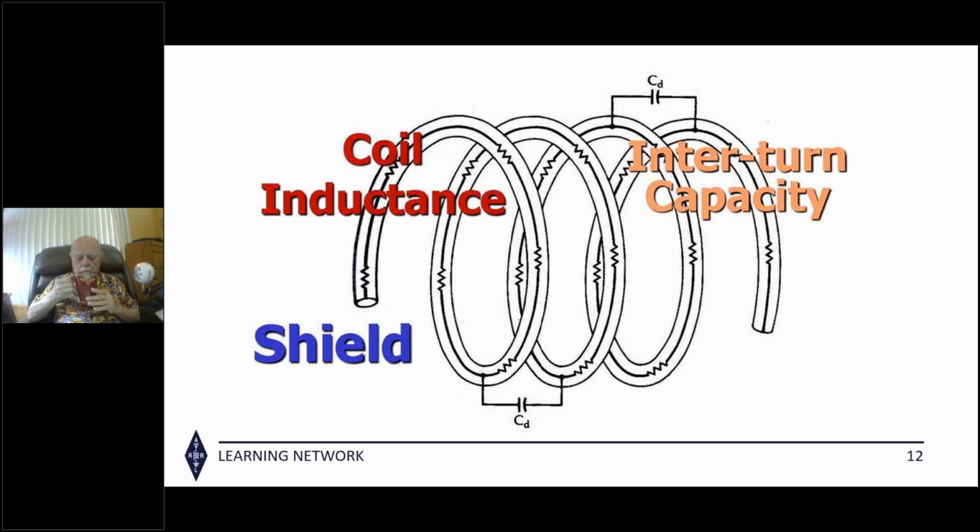Next, what about a balun at the shack? Will it keep RF from the receiver? Well, there's nothing wrong with using more than one balun. You can put them anywhere you want to. You can put one at the shack, you put one in the middle of the coax, you put one up at the feed line. They all do the same thing. They're just a blockage, and you can block it anywhere. But if the one up at the antenna is done well, chances are you don't need one down at the shack.